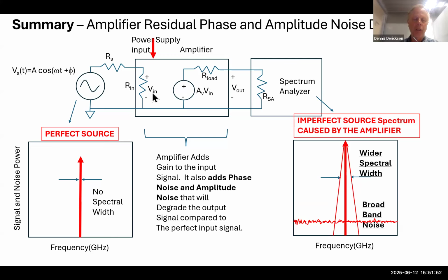The performance of this system changes as you go from linear low input signal power to a high input signal power. So you want to characterize how the AM and PM noise change as you change the input power. Another thing you want to understand, and I'll show this in future slides, is that the power supply right here can also contribute noise. And so if you're not careful, if you have a very noisy power supply, it could be that the power supply noise is a dominant noise source, not the internal shot noise, thermal noise, and 1/f noise. So I hope I gave you somewhat of an introduction here.